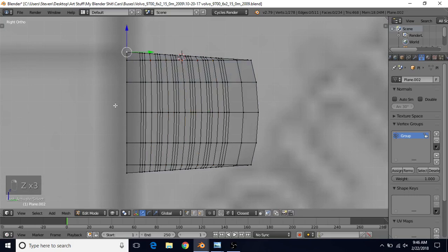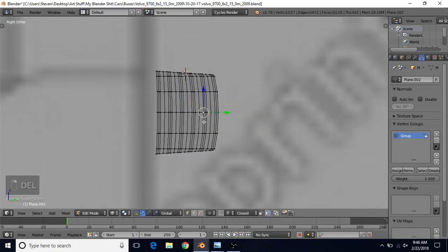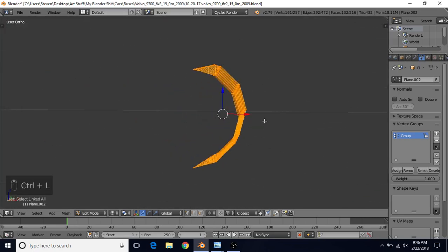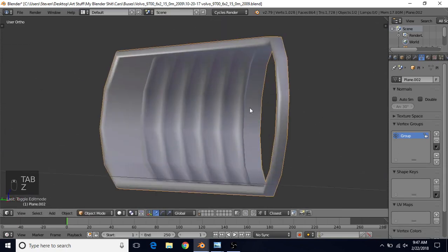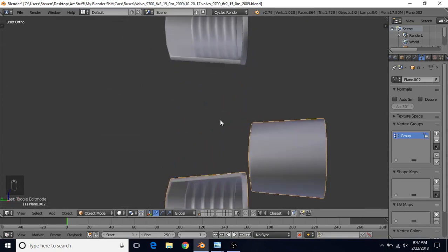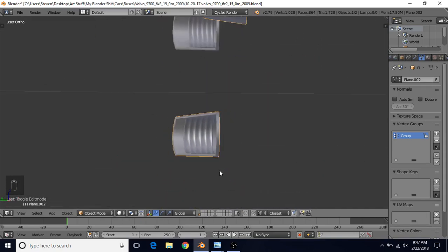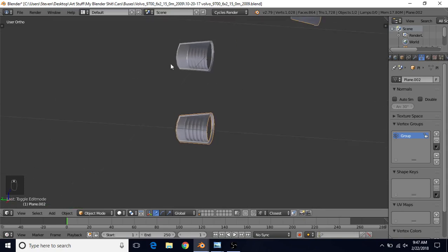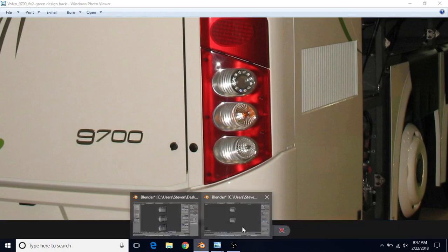And then you just want to deselect all the parts that are not part of the ribs, so Alt right click, Alt and Shift right click on both of those, delete vertices, select, Control L, bring them slightly away, and then you should have better looking ribs. So this is the one we made the first time, looks okay but not great. This is a little bit better spacing, so it looks a little nicer, I think, but it's up to you what you want to do. Just compare it to this, pick which one you like.